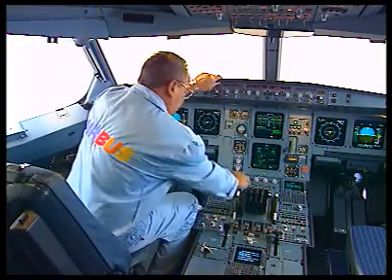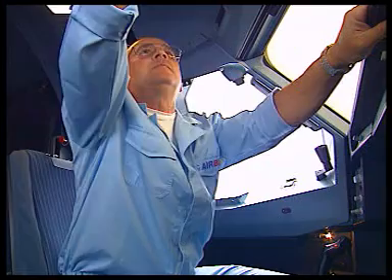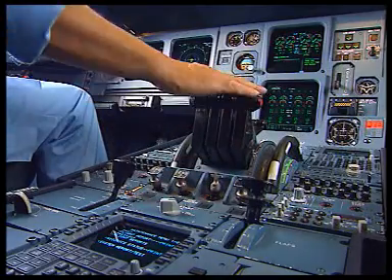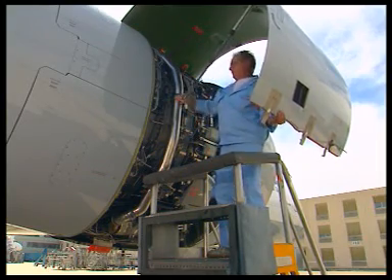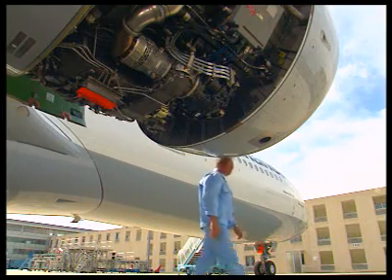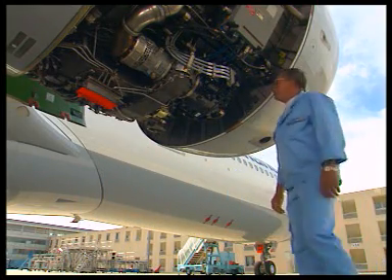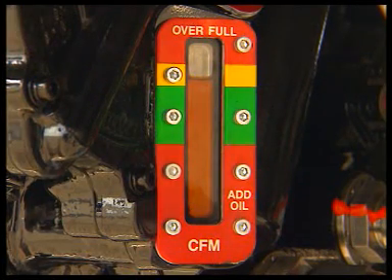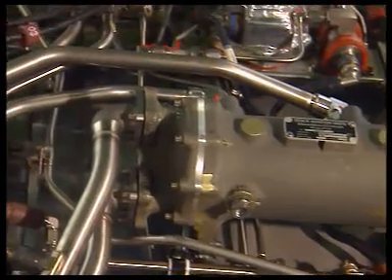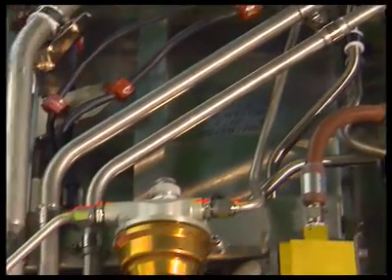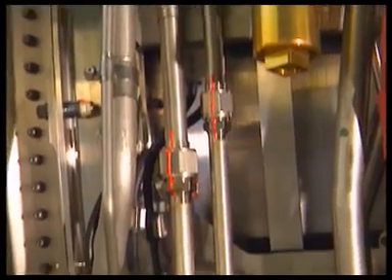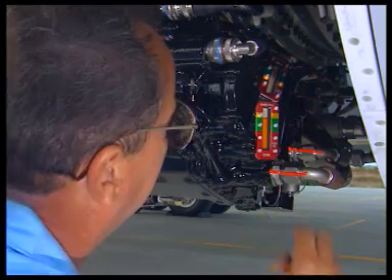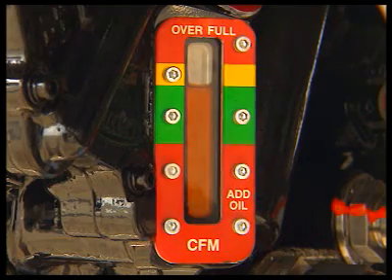Do an engine dry motoring or start the engine at idle for at least 2 minutes to allow the oil to circulate through the system and ensure that every cavity of the oil system is properly filled with oil. Let the oil level settle down for 5 minutes. The oil may be slightly above the top of the green band due to thermal oil expansion. However, the oil level may have dropped due to the presence of air in the system before the motoring. Look at the oil level sight glass again to ensure that the oil level is optimum.